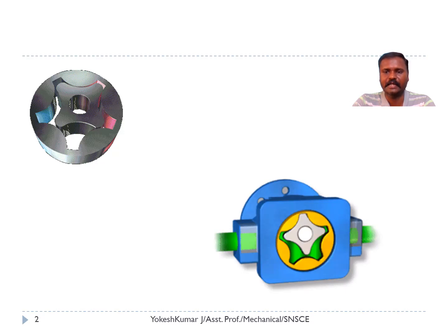So mechanical action is produced, that is, rotary motion is produced inside the gear. Finally, it is sent to the outlet port, and the oil, once it is expanded, is bypassed to the reservoir with the help of the direction control valve. This is how the external and internal gear motors function.